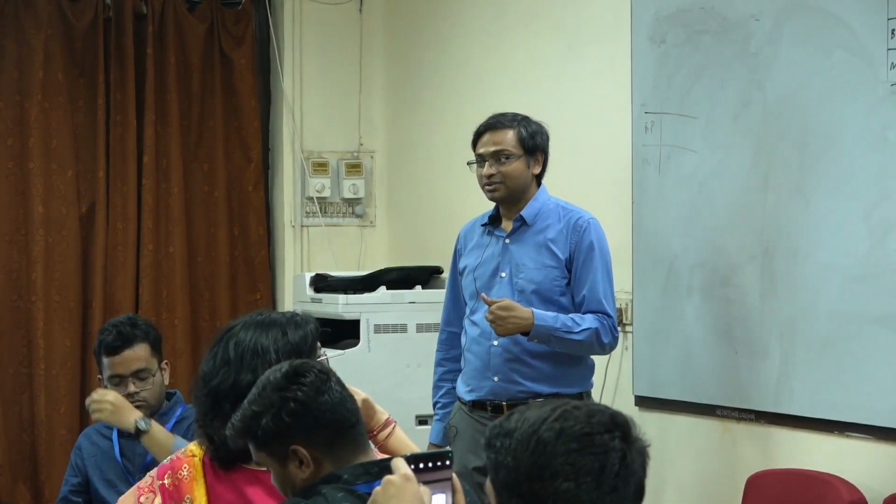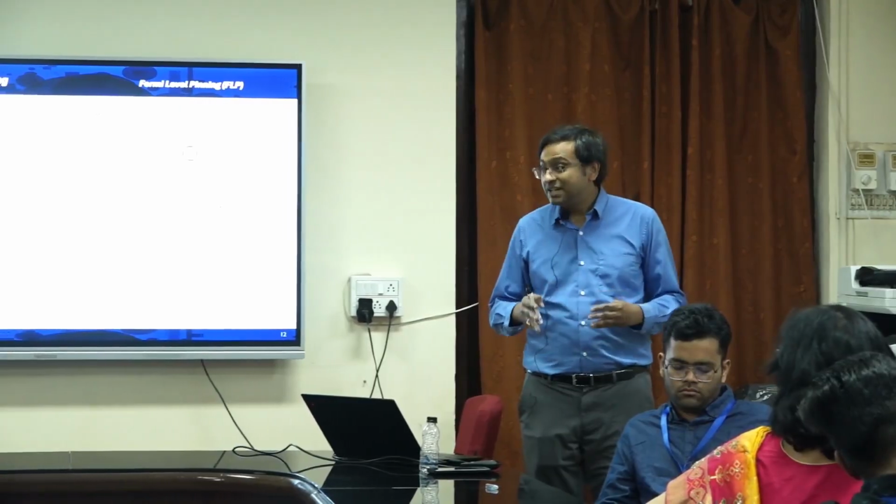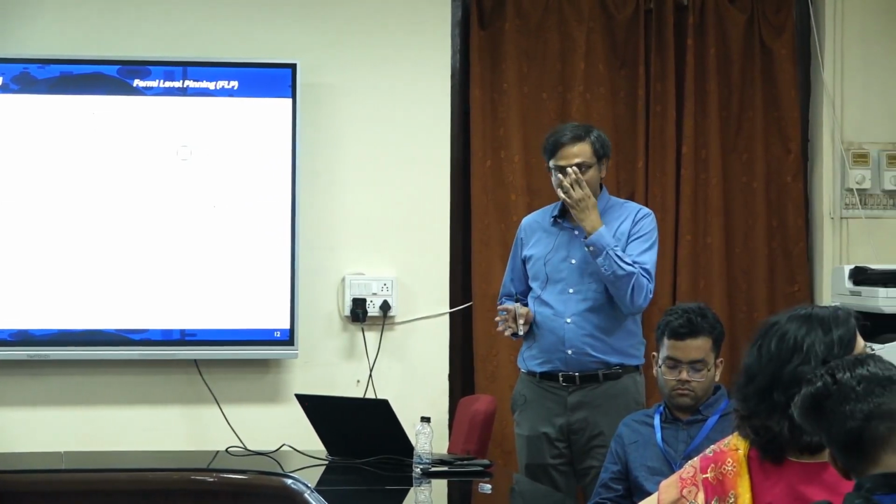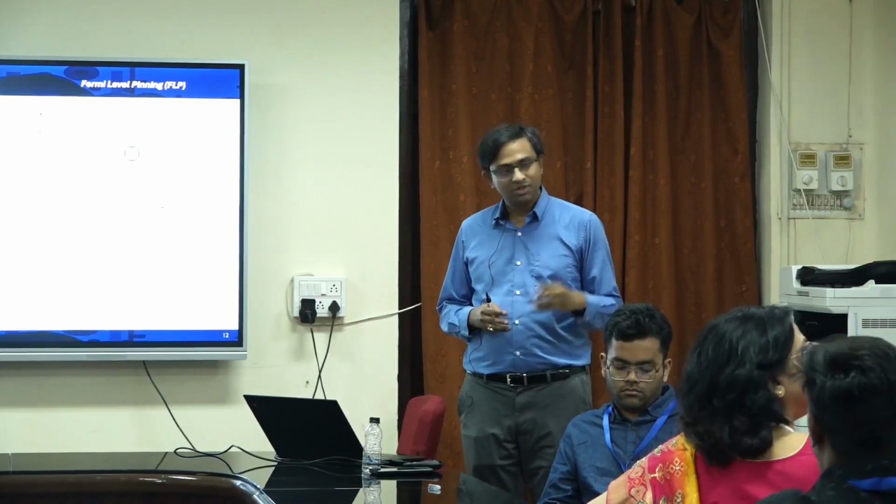So you see why it is so much more difficult to make P type contacts to 2D materials. This is our next topic. You see, there has been a lot of challenge in the community of getting a good P type contact or a P type FET, because black phosphorus is there but it is very unstable. For our MoS2, WSe2, you see the challenge.